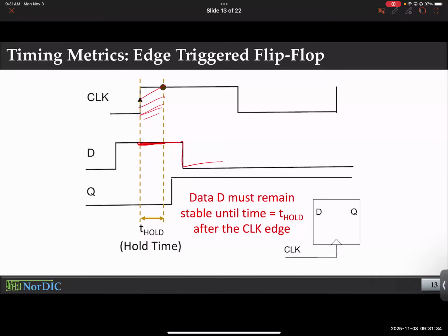So you can get it through simulation, but they also do experiment because in case you missed something in the simulation, experiments will catch it. So eventually they pack it into macroscopic parameter numbers like setup time and hold time. These are macroscopic parameters, but they are linked to fundamental charging and discharging of capacitors. That's all. Are you all good?